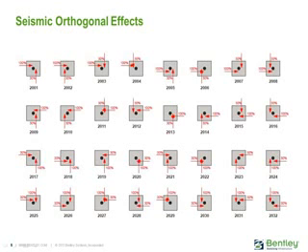Now we can use these basic primary load cases to incorporate into what we would call a seismic permutation load case to combine the loads, which would be maybe 100% of the load in one direction with 30% of the load in another direction. In STAAD.Pro, we can use a repeat load item to combine these loads together into another load case. The significance of the repeat load item is that the loads will be combined before the model is analyzed, so you get the true effect of the loads acting simultaneously.